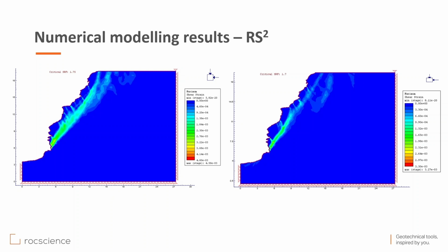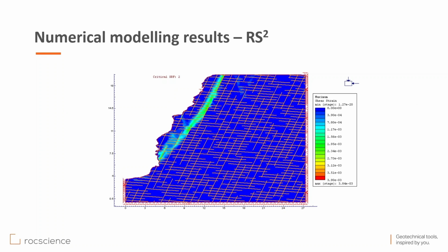During the modeling, we tried several model runs using a homogeneous material model, and with several variations we tried to introduce the documented discontinuity, as I mentioned earlier. Here you can see the models using the discontinuity sets. Since that is not the focus of our presentation, I will not go into details, but once the model has been constructed, the shear strengths of all the component materials are iteratively increased or decreased by a strength reduction factor until the slope fails. So we used the